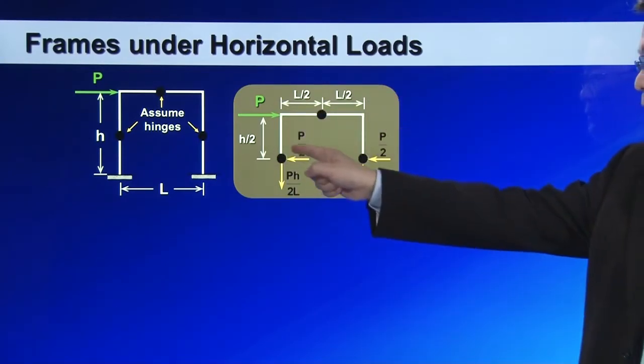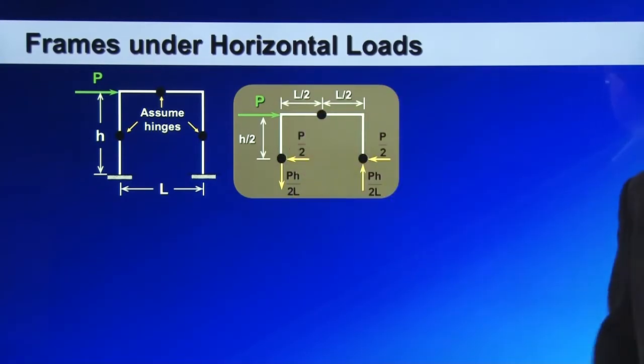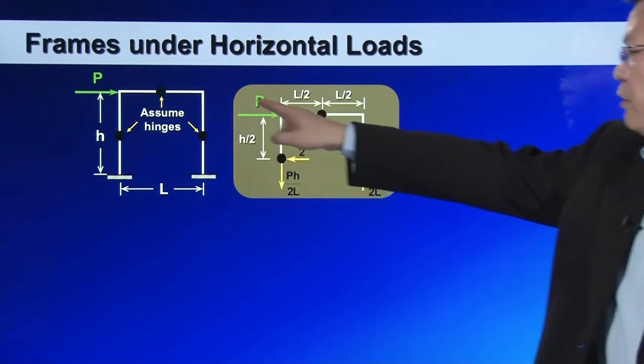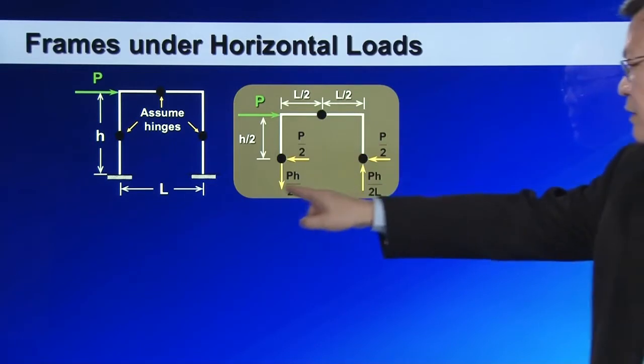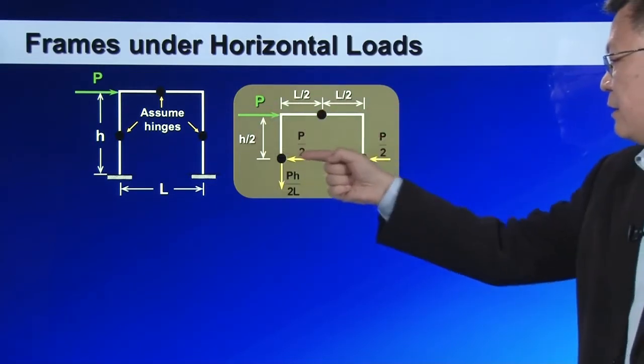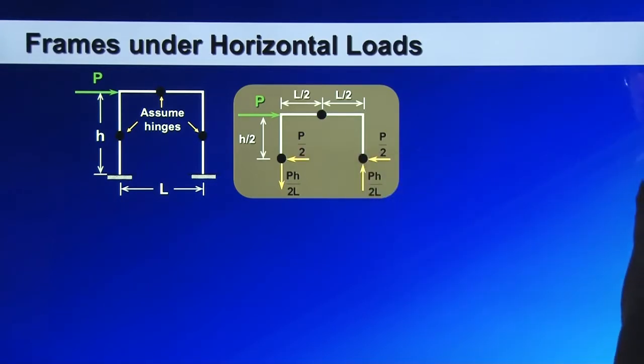Then you will obtain the vertical force. Then you go to this inflection point, do a free body diagram on this left part or right part, and then you can get the horizontal force. After that, you just do equilibrium, and then you get the rest of the two forces.